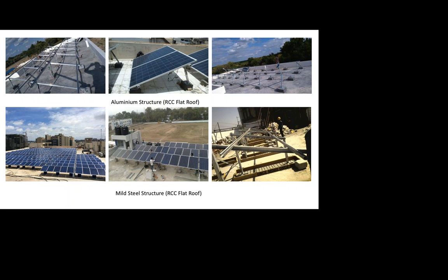And for pre-galvanized, we understand that at the shearing points, at the punching points, where zinc is removed, it catches a little bit of rust. Even if you want to be safeguarded against that, you can use a zinc primer or a spray, and that too at the manufacturing, at the stacking, at the dispatch level itself, and not at site. Because handling something at the factory is much easier than handling it at site, where it gets spread out all across acres of land.